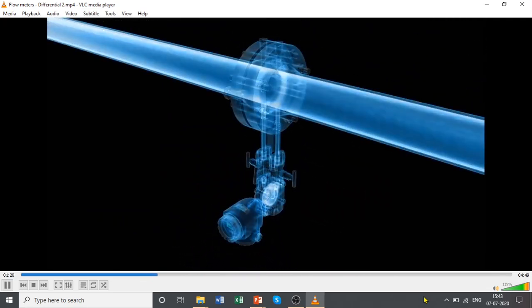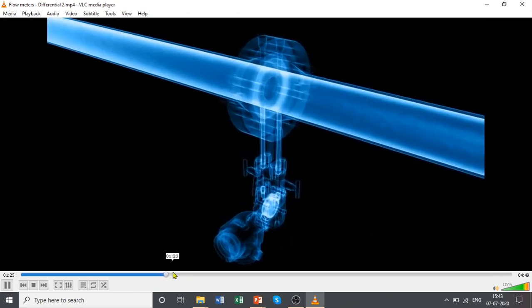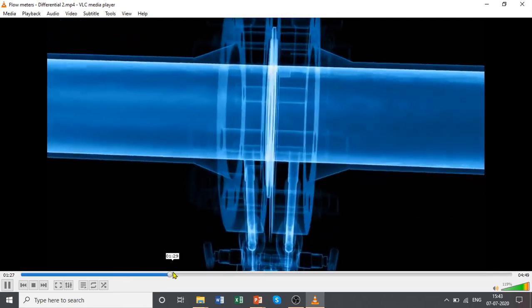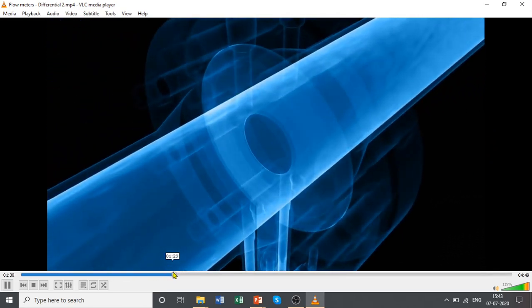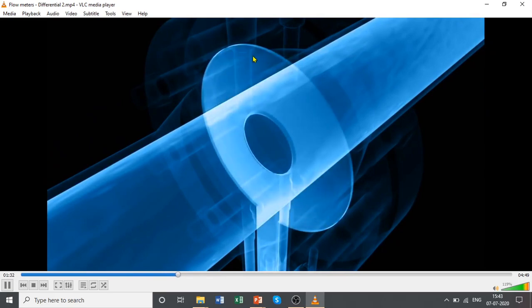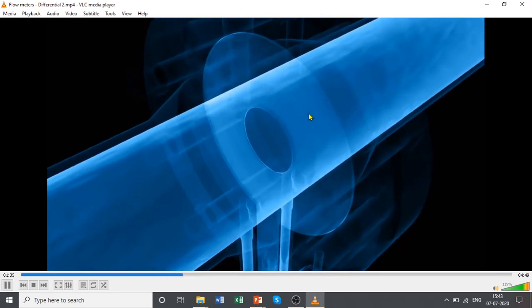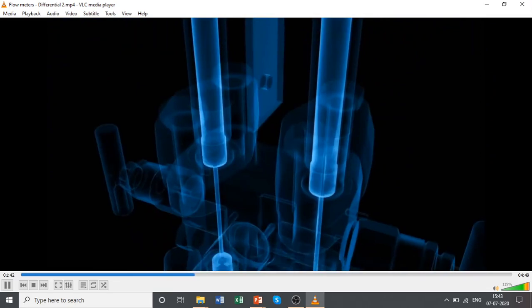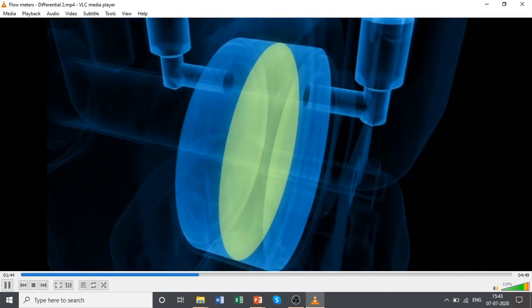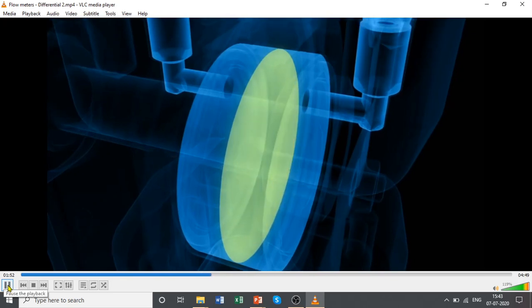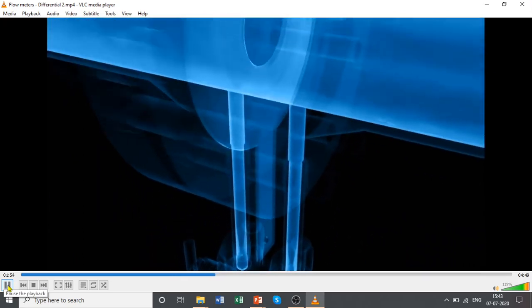Here is how this measurement method works. Differential pressure flow meters have an artificial restriction integrated into the measuring tube, illustrated here by the example of an orifice plate. This is an orifice plate. Two holes are located in the pipe wall, one before and one after the orifice plate. Two separate tubes connect these holes to a differential pressure sensor with its two pressure chambers separated by a diaphragm. The tiniest pressure differences in the flowing fluid can be precisely measured.